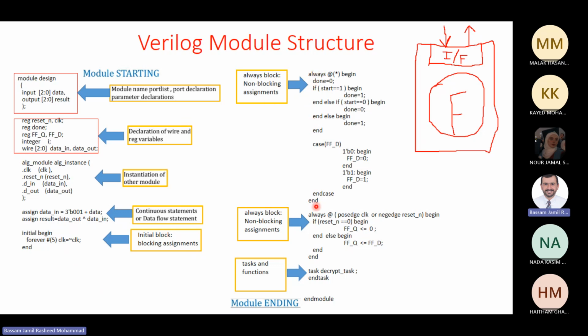Now, the always block represents either a combinational circuit or a sequential circuit. So I can have combinational. Combinational like what? An adder, a multiplier (unless it is a sophisticated multiplier with a control, that is a different matter), a shifter, a comparator. Those are combinational circuits. And sequential circuits are like a counter. We talked about shifting in combinational circuits, but if I have, for example, a serial shifter that shifts the data right, or a linear feedback shift register, it has to be a sequential circuit.